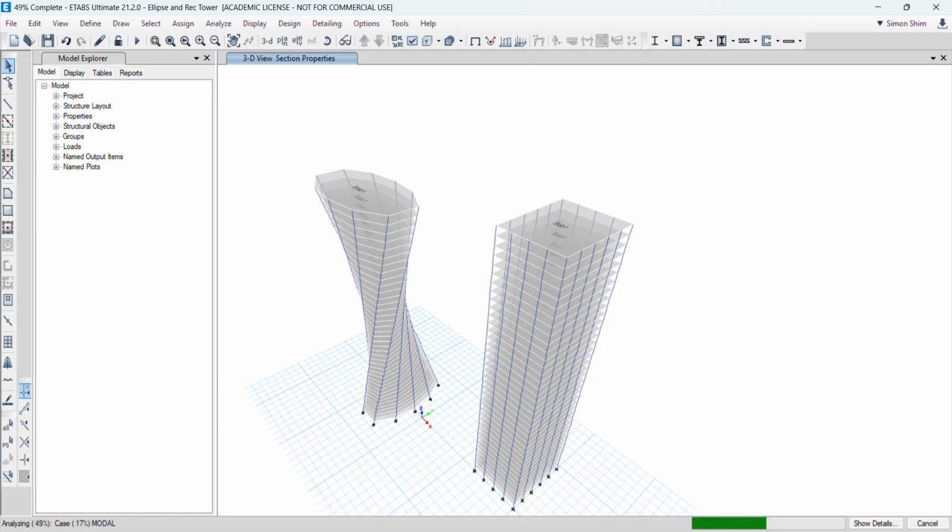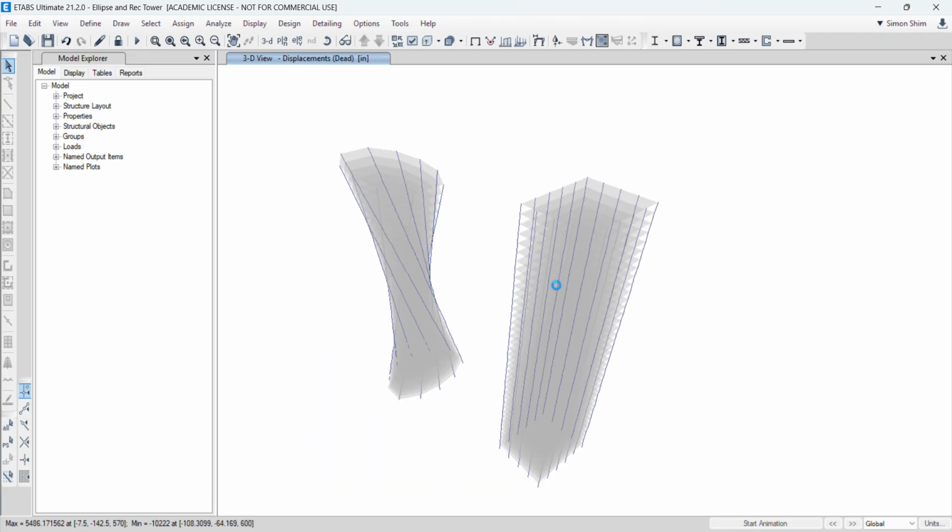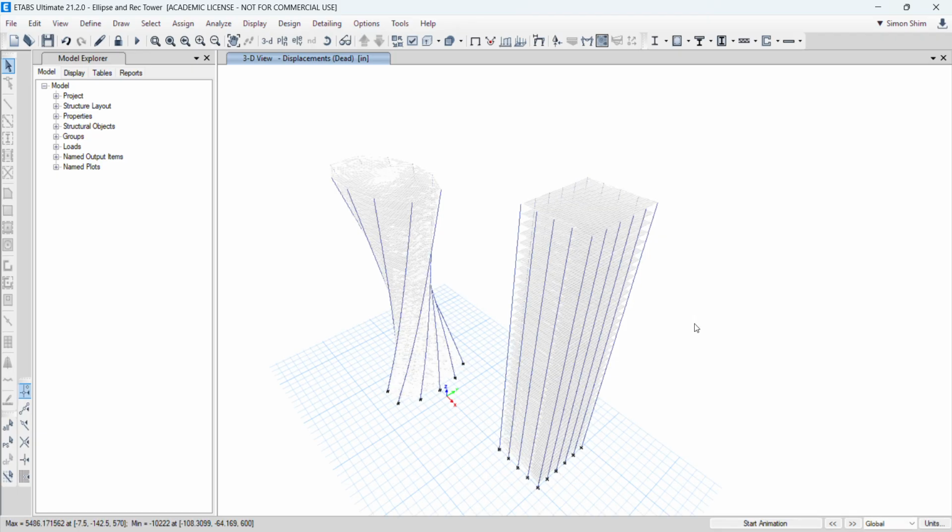Wow. Yeah, modal analysis is on by default. So I'm sure this one is gonna show a long period. I'm gonna just pause and wait. Alright, so ETABS finished the analysis. Okay, next time I'm gonna turn off the modal analysis. This is not the dynamic analysis introduction. This is just a static gravity load takedown.